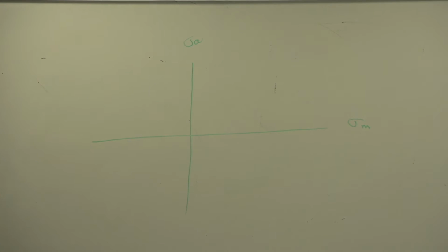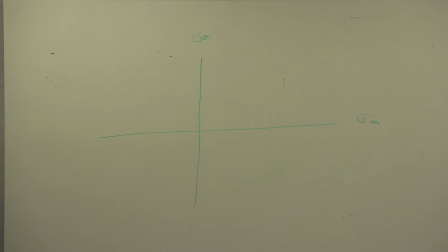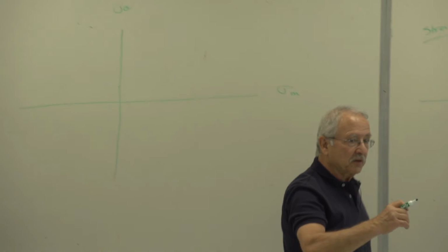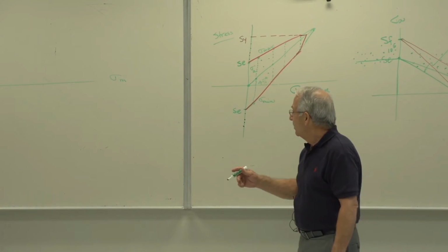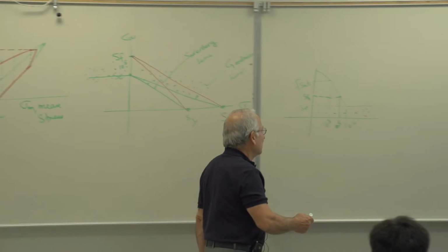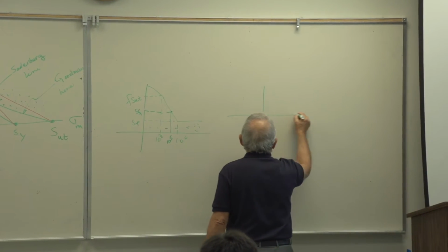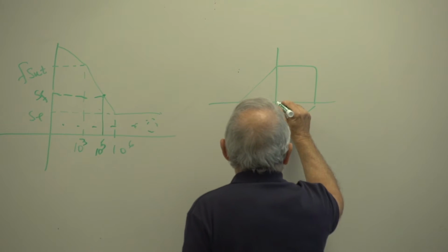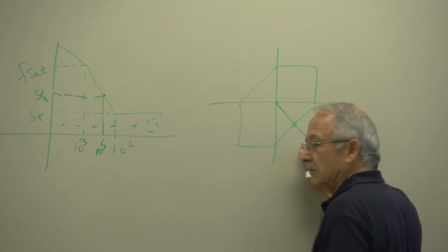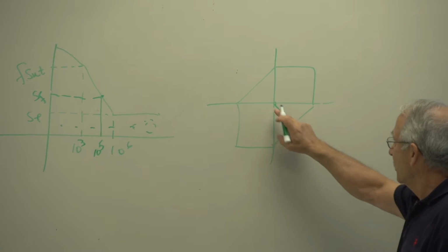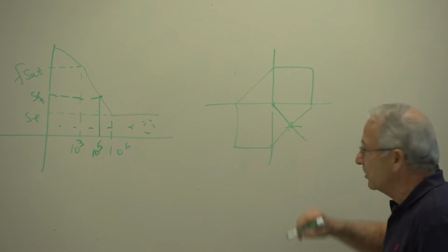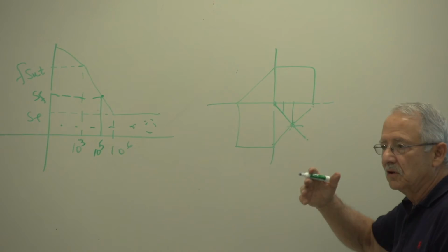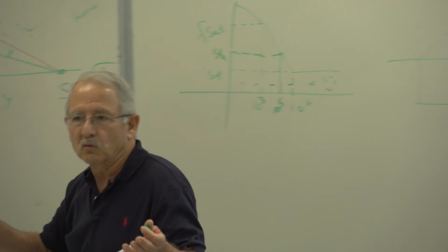So we said, let's draw our strength lines. These are our strength lines. What I'm about to do is exactly what we did when we applied failure theories in static loading. For example, in maximum shear stress, this is what we did. We said, here is the failure locus. There is my load line. Remember that? Strength line, load line. You draw the load line, you draw the strength line. Whenever they cross, that's your limiting value. And you use that to find factors of safety or say whether the part has failed or whatever.